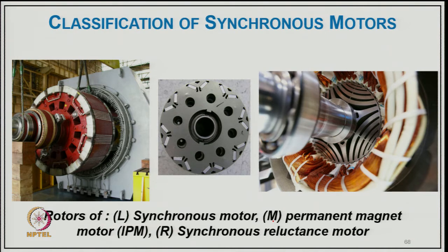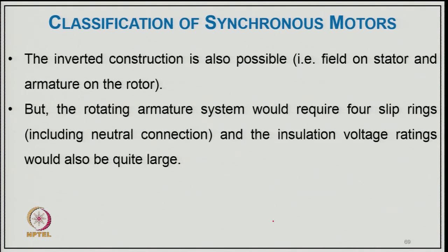So, this is a synchronous reluctance motor that has recently come from ABB and Siemens. They have become very popular because they are more efficient than induction motors and more robust than other synchronous motors, and this is typically the interior type of permanent magnet motor for electric vehicle, and this is typically a conventional synchronous motor. You can see that synchronous motors are day by day becoming popular for the majority of applications, replacing many applications, especially even the squirrel cage induction motor.